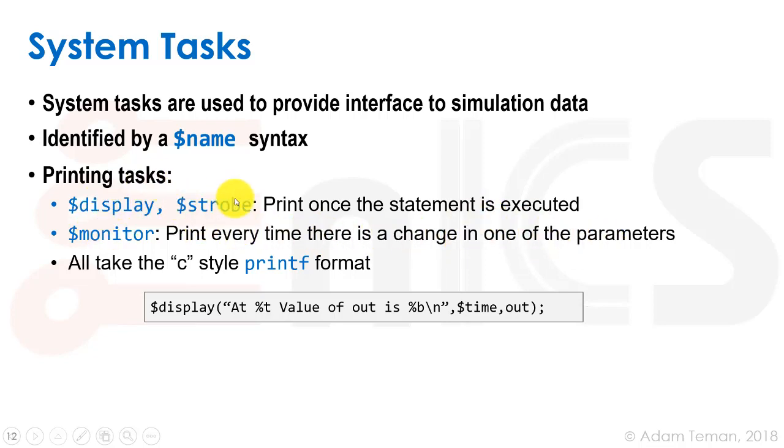Since these are all print type of commands, they take a C-style printf format. For example, we can do $display, then we use a pair of quotation marks.